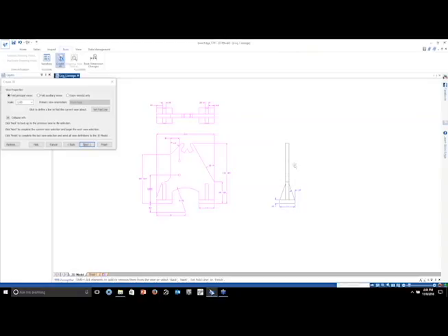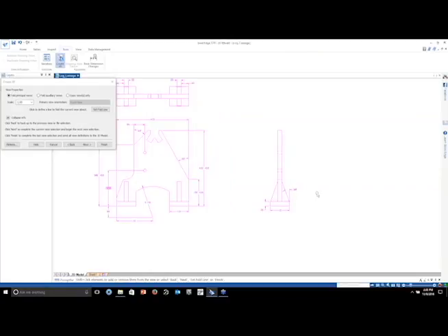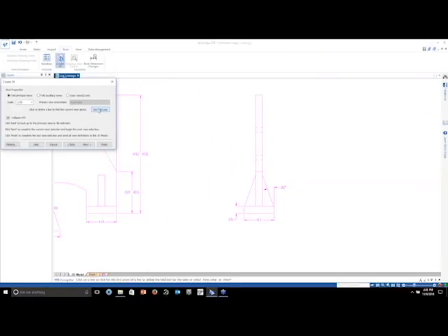This is my side view. And this one I'm going to set a fold line. What I'm doing here is defining where I want this to line up on this view. By default, it'll just line it up on this edge, but I want it to be in the middle, so I'm just going to say I want that midpoint. So there's my center points, and I'll just say finish. What it's going to do is take that sketch geometry from the 2D and bring it into the environment, which is an ANSI metric for this scenario. And again, I told this view to line up on the center.